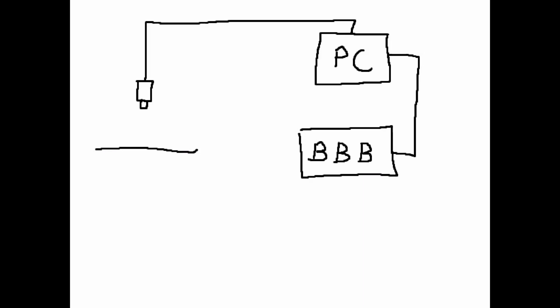The Beaglebone Black solves this problem in two ways. Things like the pulse width modulation ports have their own clock. Thus, if they're set to output a waveform of a certain pulse width and frequency, they will continue to do so even if the process that requested it is swapped in and out of memory.